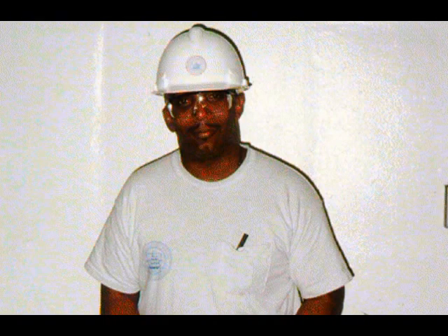Joe knows that he has to lock out the pump before he changes the impeller, but he has misplaced his own lock. Joe borrows Fred's lock. What do you think of Joe's decision? While it may seem inconvenient at the time, it is a better idea to get a new lock than to borrow someone else's. To ensure his own safety, Joe should take the time to find his own lock or to get a new one. There should be only one key per lock.